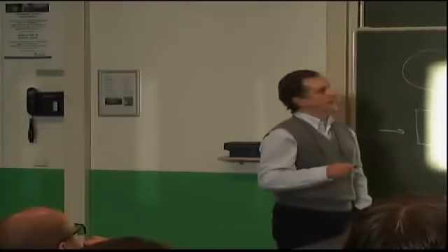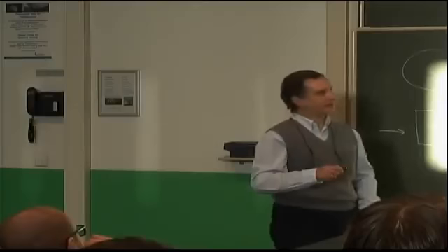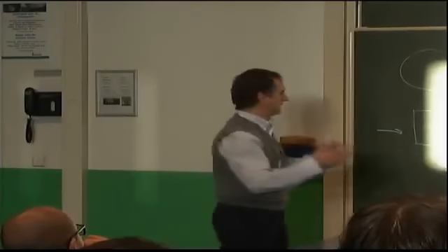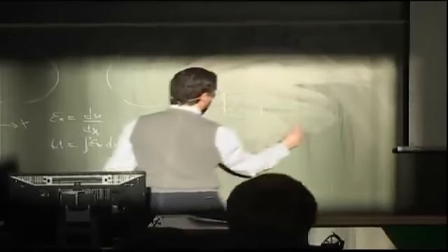The reason for that, let's have a generic discussion on number of terms. If the stiffness of the inner layup is similar to the stiffness of the outer layup, then it will deform in a way that's similar to a single material. It's when the stiffnesses are very different that it makes a big difference, because let's say the center portion was extremely stiff, while the outer portion was very soft under some load.